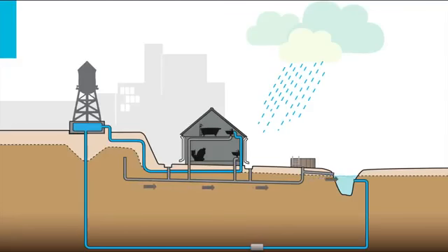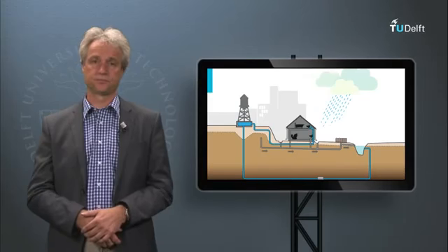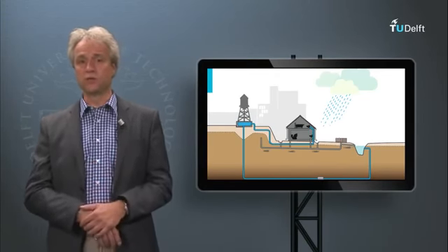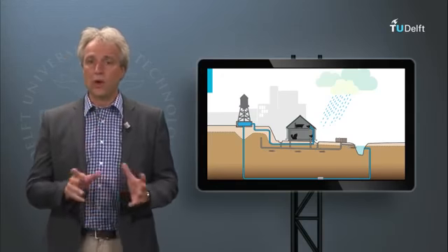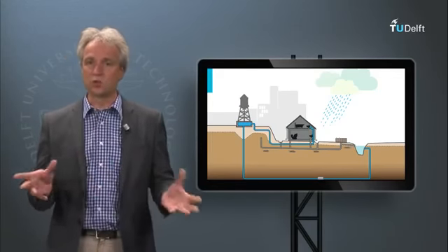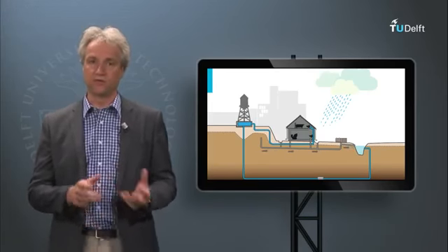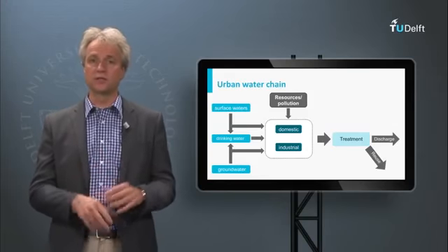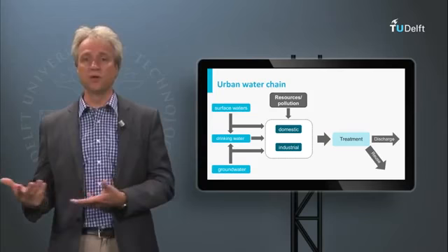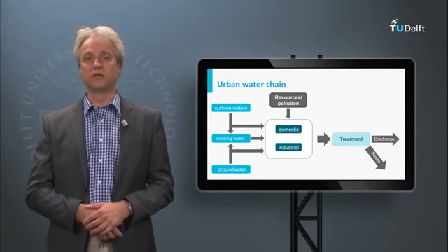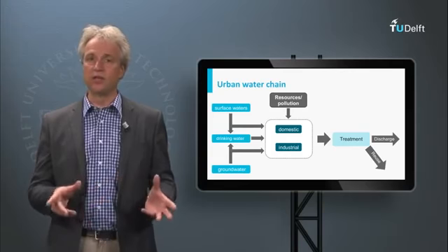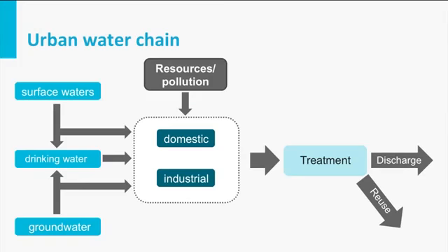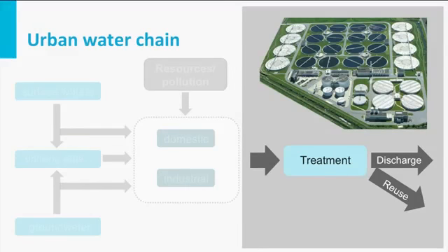Collection of the used urban waters is generally done by means of an extensive sewage network, which conveys the urban sewage to the site of treatment. The term used urban waters over wastewater in fact better describes the state of the water and therefore has my strong preference. Moreover, wastewater implicitly is negatively valued, water that is wasted, and it needs treatment prior to discharge into an environmental sink. Used urban waters is more positive and calls for treatment for reuse. This can be the water itself or the various pollutants that can be recovered as a resource. In fact, the term used urban waters better fits in the urban water cycle idea, the central theme of our entire course. The collected sewage is treated at a sewage treatment plant or wastewater treatment plant.